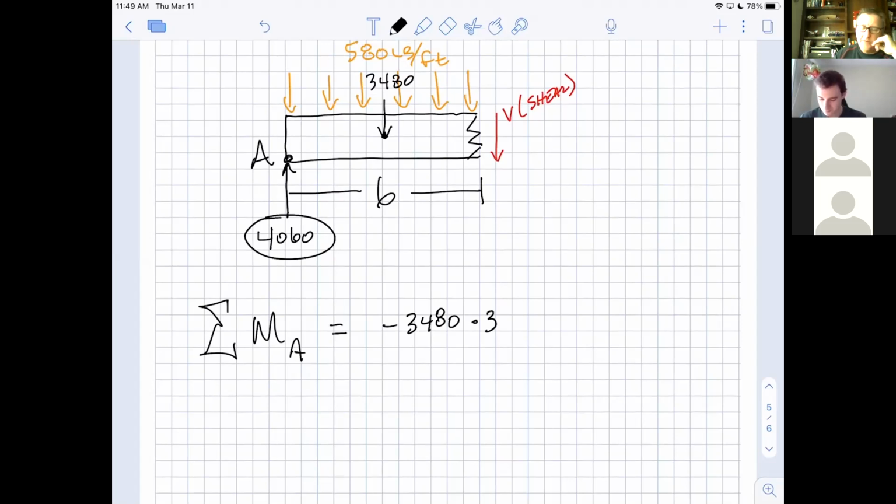So do you understand that, again, because the beam is connected, that there would be a moment? In other words, if this beam is actually connected, just like the shear, watch this carefully, if this beam wants to rotate down, and let's pretend we're just looking at the left side, is that side going to be allowed to rotate down? The answer is no, because it's being lifted up by this other side over here, isn't it? So do you see why I would need to add this moment to the support?